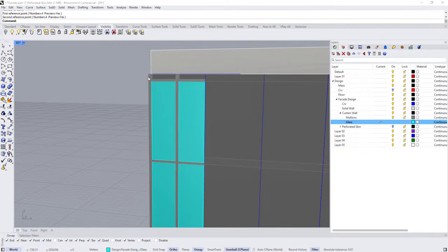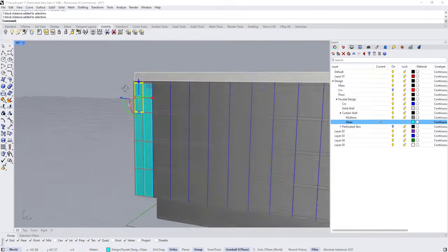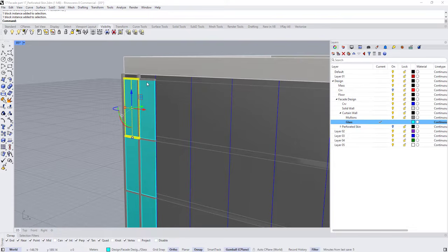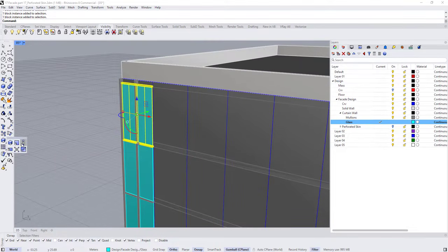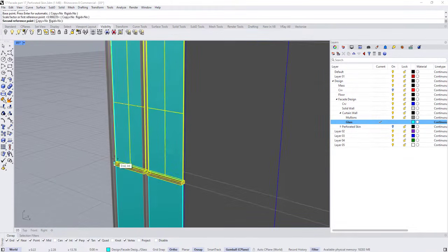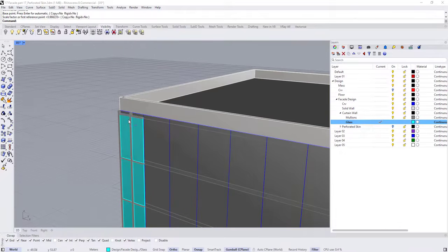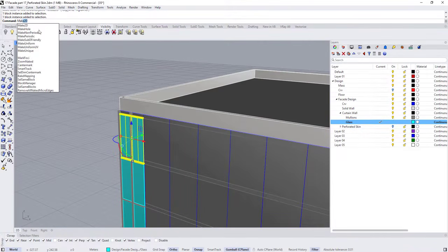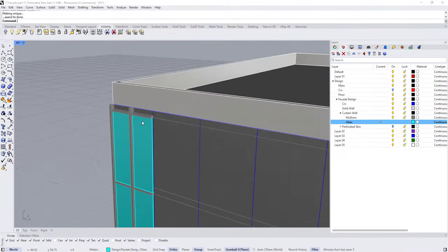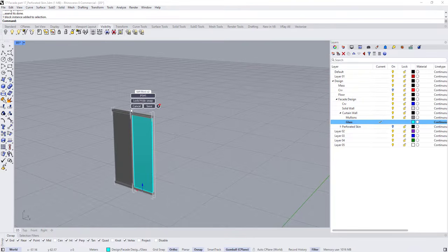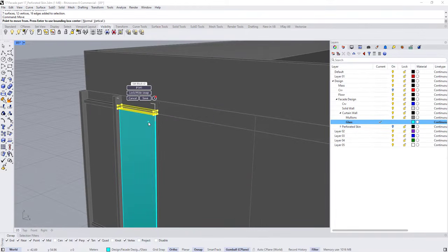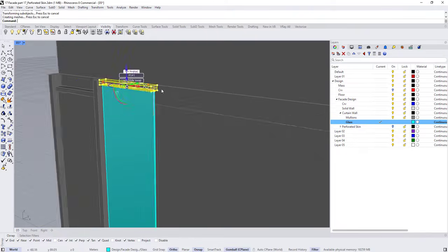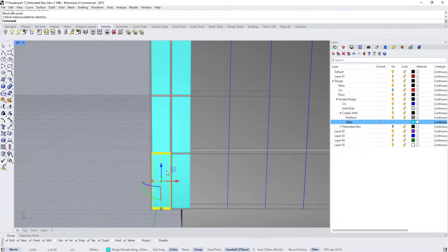So it looks okay except for the top part. Okay, so for the top part, I'm just going to scale it in one direction for now. So it should scale in one direction. Or you know what? Let's select this and type make unique. Now double click, show everything, hold Ctrl Shift, select this, type move, press V for vertical and move it up to be something like this.